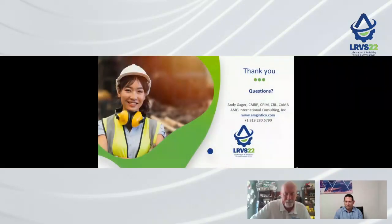But once we identify the assets, the critical processes, or the critical systems, that's when I can link our risk assessment to our physical assets, and we can determine the most appropriate maintenance strategies to address that risk. Ultimately, our goal is to eliminate that risk or mitigate or minimize the potential failure or the consequence of that failure. I hope that answers your question.